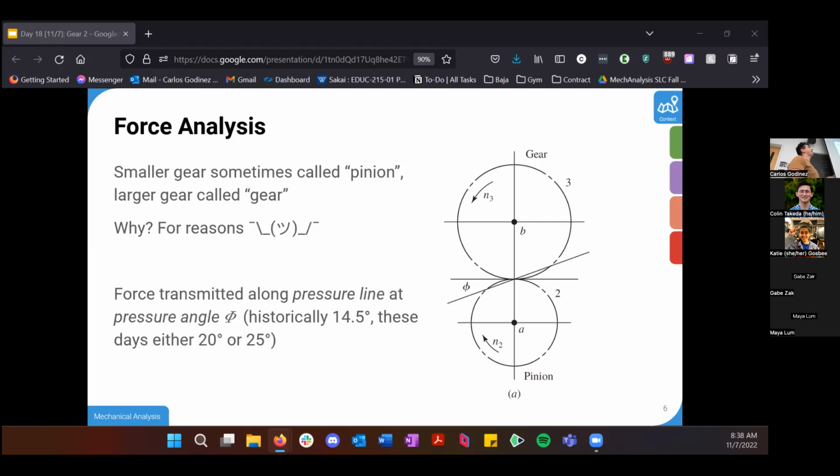Yeah. As a fun fact, they primarily have a prime number of teeth on their gears, meaning that the same gear, when it's in mesh with another gear, is very rarely coming into contact with the same gear teeth. For example, if you have a 20 teeth gear in mesh with another 20 teeth gear, the same gear teeth are going to be coming into contact each individual time. But if you change it, you'll have rotating ones. And if you have it prime, the same gear teeth will be coming in contact even less because you don't have the very common multiples.